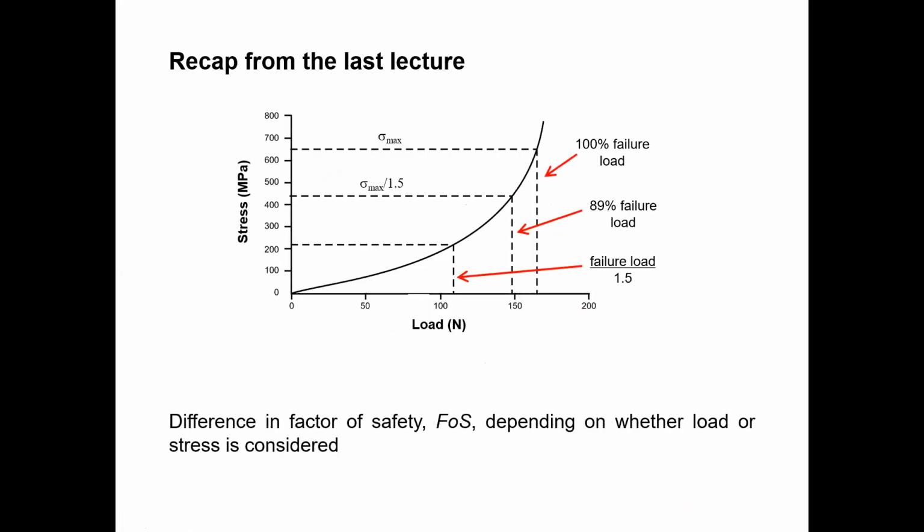Yes. So then we discussed the non-linearity between the stress and loading. At that time also you can't use the Kf value on the stress. So I told you to apply that fatigue stress concentration factor to the load. If you are going to calculate the factor of safety using stress, that is not correct if it is non-linear. So you can see here the load and stress relationship is not linear, it is non-linear. So then you can't use stress to find out the factor of safety.